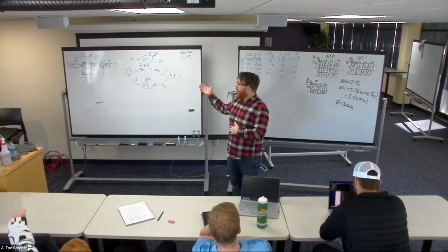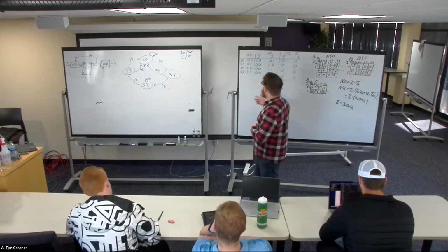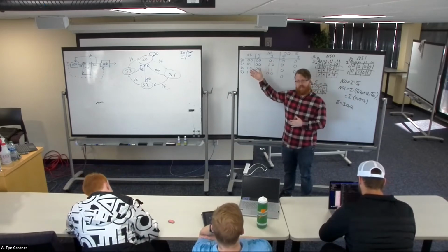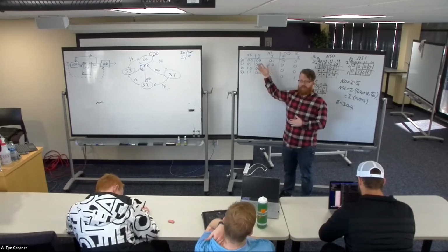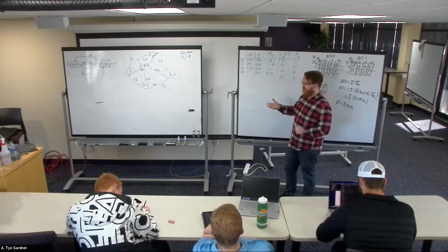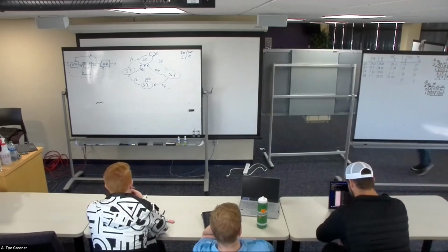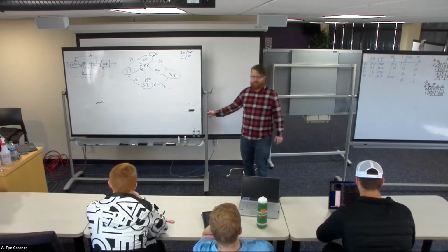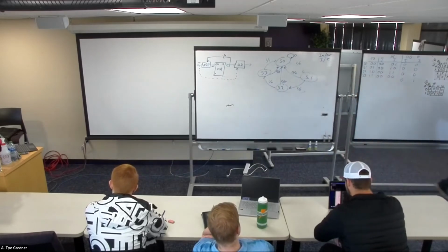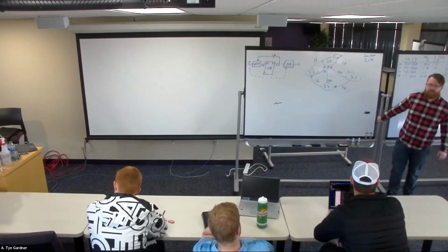So now I'm going to switch over and we're going to start talking about the VHDL of state machines, because as I said, 2 inputs is fine. But as soon as we have, say, 5 states, now I need 3 bits, and then with, say, 2 inputs, you would have to be able to do a 5 variable K-map, which I haven't taught this semester, so you're out of luck. So we have to go back and start thinking about it in terms of VHDL. How do we simplify this so that we can design complex state machines without having to learn more advanced digital logic concepts? In many ways, VHDL is what allows us to teach this course as an essentially freshman level course instead of making it a junior level course as mine is.